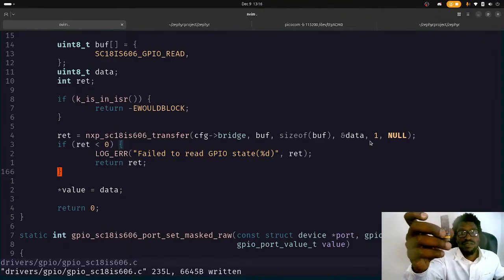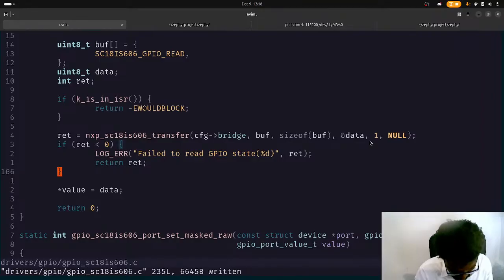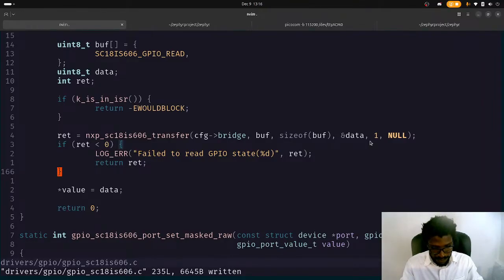So this is my logic analyzer, and it does use USB-C. I do have USB-C connected, yeah. So I'm going to hook this up. The white one goes to ground or 0.